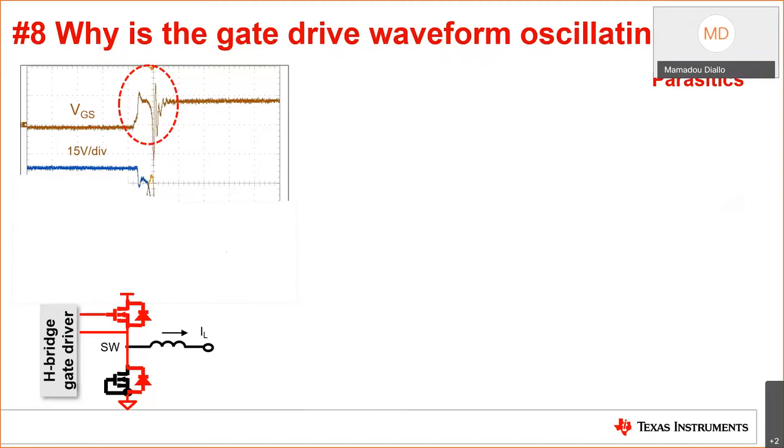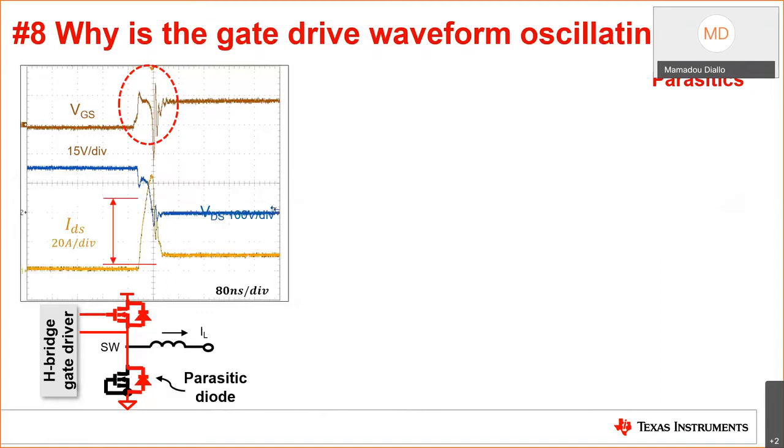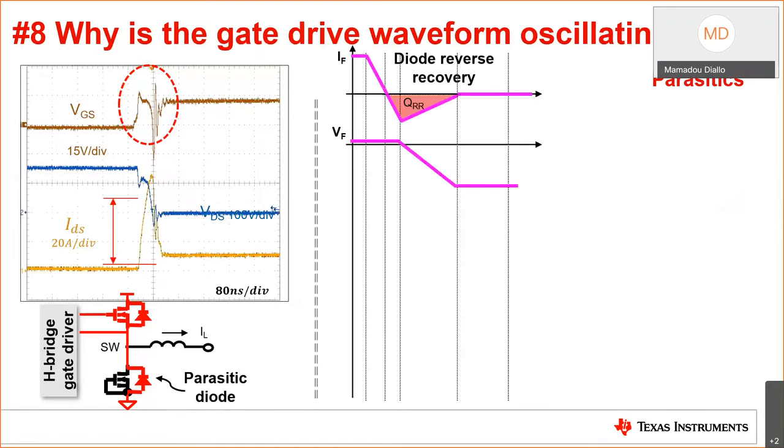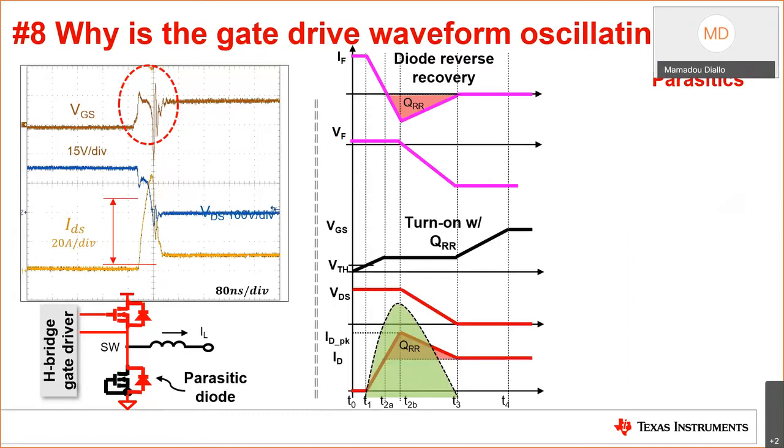So what's happening essentially is under hard switching applications, the body diode reverse recovery will occur. The critical waveform is shown in the top middle here. This reverse recovery current will be reflected at the top switch, generating more turn-on losses. With two experiment results for body diode of MOSFET and anti-parallel diode of IGBTs, you could see a tremendous amount of inrush current, which is caused by the reverse recovery.